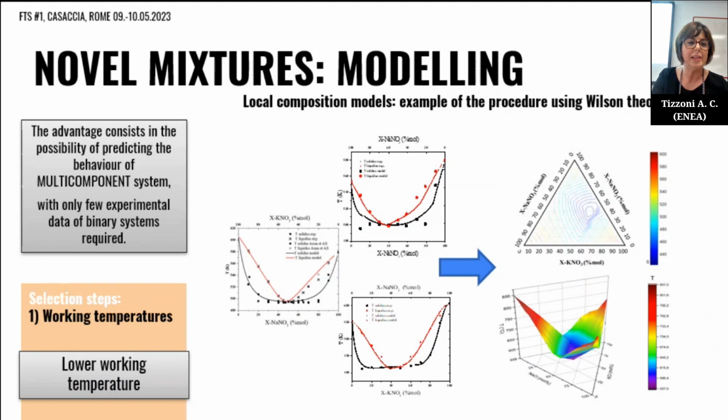So regarding the lower working temperature, here I reported an example of the procedure using Wilson theory. In fact, using the approach of local composition models, it is possible to assume that the local composition around a molecule is different from the medium composition of the mixture.